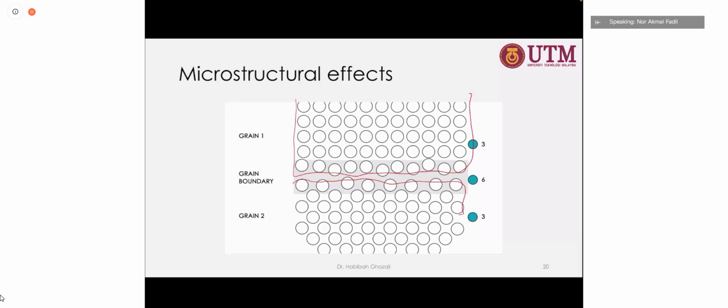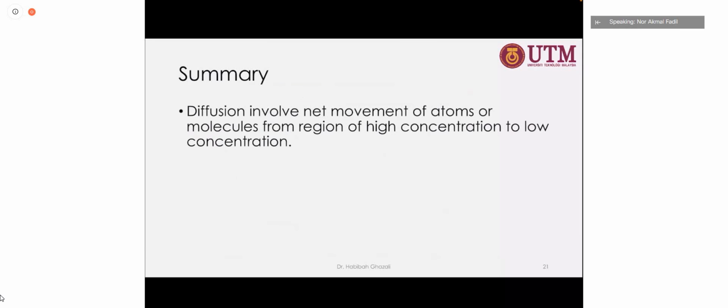That's the reason it requires very low energy to move from one part to another. If all regions receive similar energy, or temperature, since there are abundant vacancies in this part, the atoms at the grain boundary will move faster than in the grain. This is what happens in diffusion.